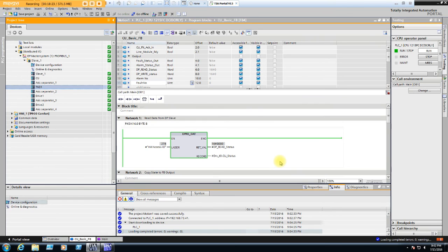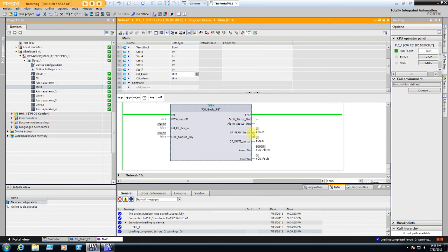He can say, hey, it's saying that the I/O module X has some sort of fault on it, and obviously if it's got important I/O, the line's not going to run or run right, and it leads them right to the problem. So you can get as fancy as you want. We've actually used these where all the I/O data comes out of the block, so you can see each point individually as a bool.